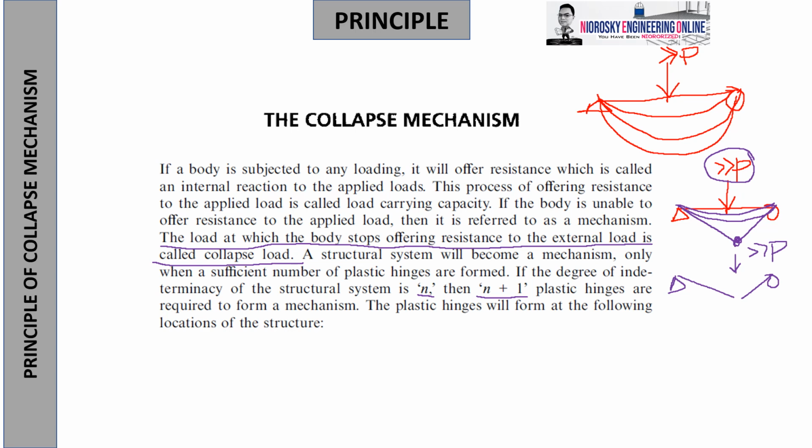And also, to follow the statement, a structural system will become a mechanism only when a sufficient number of plastic hinges are formed. You notice that in this region, the support, and the area where the load is being applied, assuming that it is a single concentrated load, there is some hinging or rotation that takes place with respect to the area.